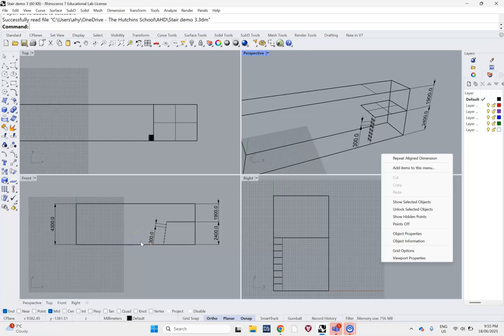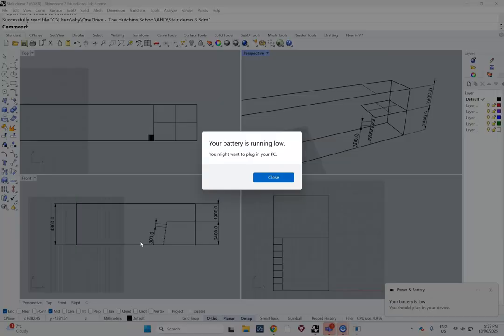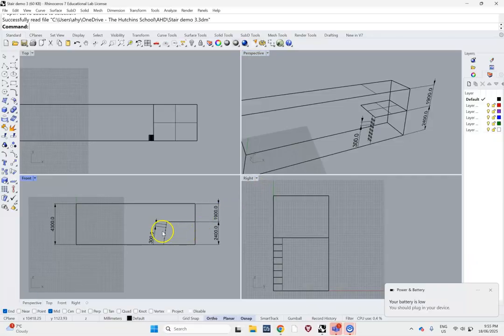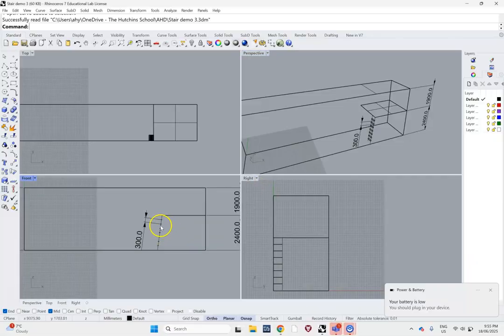quite big rises. You could go for about 250 to 300 millimeters in height. So you're really pushing that height because it's for young people. It's not for old people like me or much older than me. You've got to think about the demographic that would be using this. Okay, so anyway, I've just put a little step ladder, and these are 300 millimeters apart. And so you can see, that would be around about 400 millimeters in width.